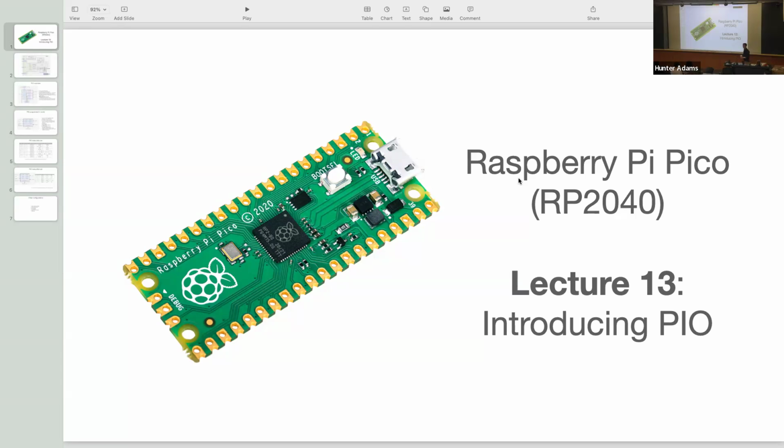Bruce? Oh yeah, when you are doing this integration, remember that the DAC has 2 output channels, output channel A and output channel B. In the first lab, we just happened to use output channel B, but for no good reason really. And the DMA demo, I believe, uses the other output channel. So in the event that you aren't hearing anything come out of that DMA demo and you're not sure why, just make sure that you are looking at the correct output channel of the DAC.